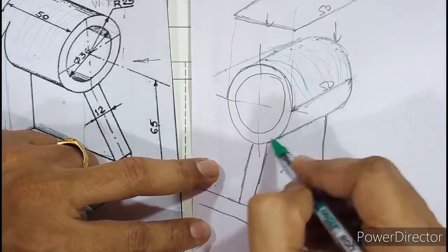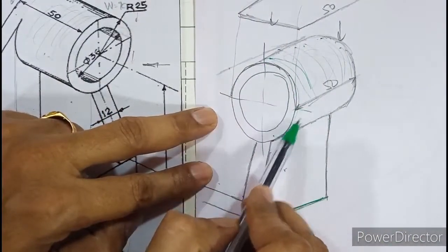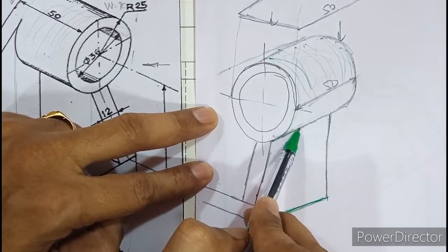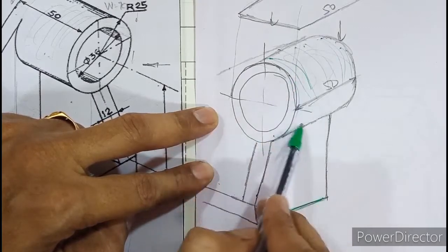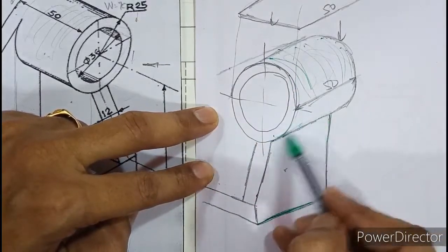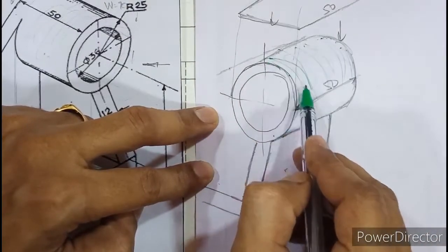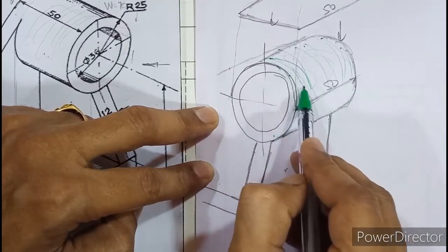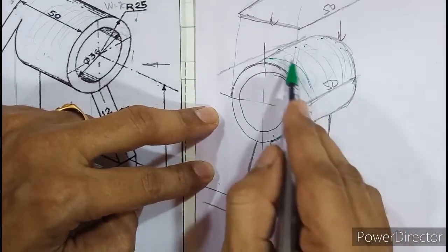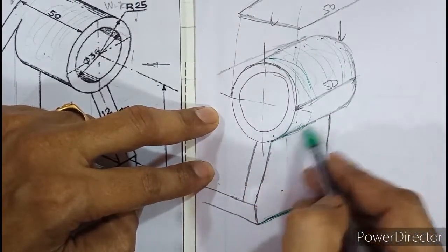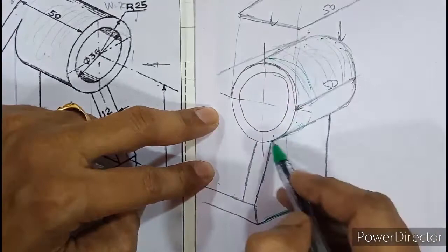Or you can say wherever the cylinder and the rib intersect, there is an edge, isn't it? See, try to move your hand on this surface. This part is circular. When you move your hand down, you suddenly change over to a flat surface. That sudden change means there is an edge, and that edge in the top view is same as this one, both are overlapping. Moving smoothly on a curved surface, suddenly at a point you move on a vertical surface. So the intersection of circular and vertical surface will form an edge, and that edge you cannot see from the top view because the cylinder is in between the observer and that edge.